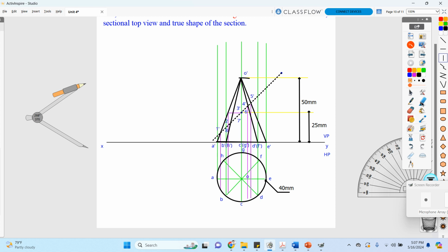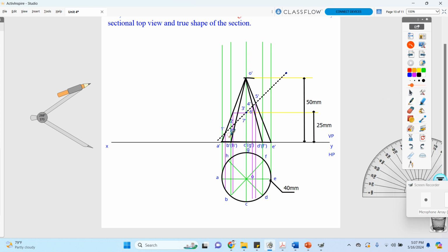Okay, so for this I am going to mark 1 intersecting with my A. This is my first point. Now considering 2, which is going to intersect over here, then 3 we want to take on the axis. For that only we have considered a reference. For this we are going to take our compass, place it over here, then move and measure this distance, and you just take it to the axis.